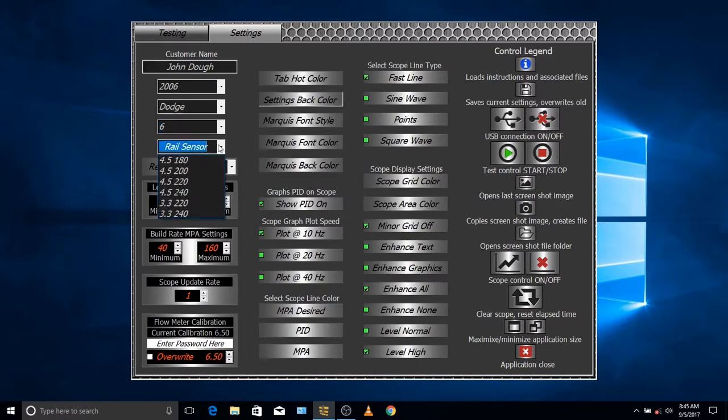That brings us to our rail pressure sensor selection, and we're going to discuss this just a little bit. Why do we not have it auto select this? Well, for some performance applications and racing applications, it's very good to use this tool for high performance applications. Guys are putting higher resolution sensors in here, and typically what we would do is use a higher resolution sensor, and then set the rail pressure relief valve to open at a lower range. So in data logging, you could pick up pressure spikes and you could see exactly what's going on.